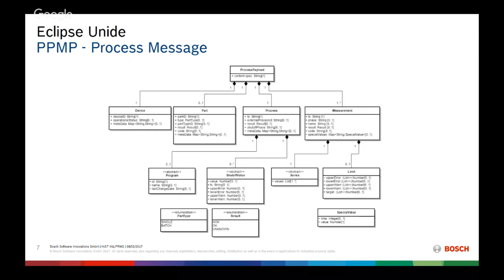For a tightening process, it's not relevant to have torque related to time, but it's relevant to have torque related to an angle, and this is what you can compare between several processes. And also you can set here the limits. In addition to the measurement payload, it's not just a single value for an upper or lower error or warning level, but you can set here an array of values to maybe have a cuff around the values you set there.